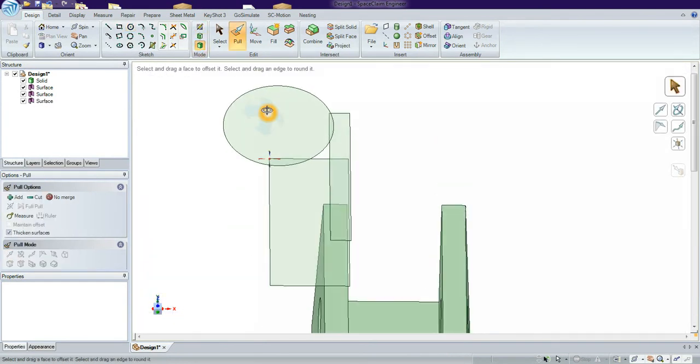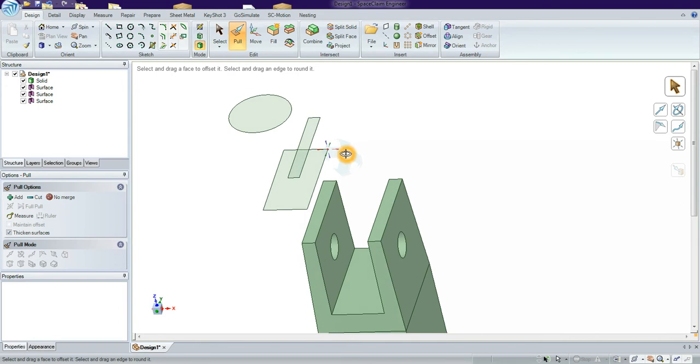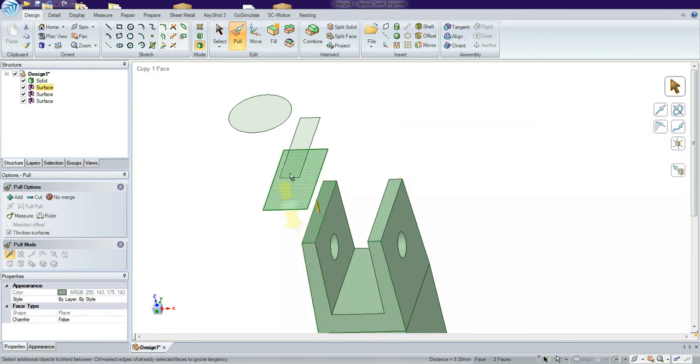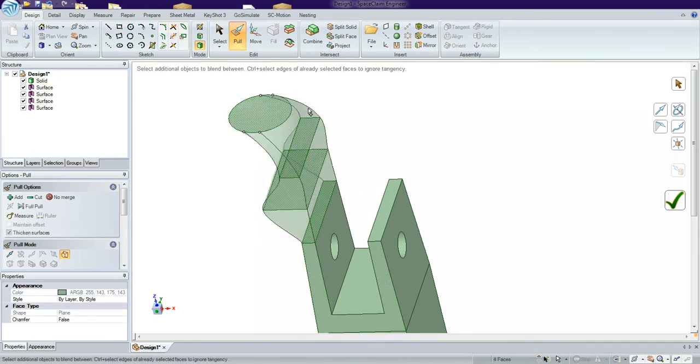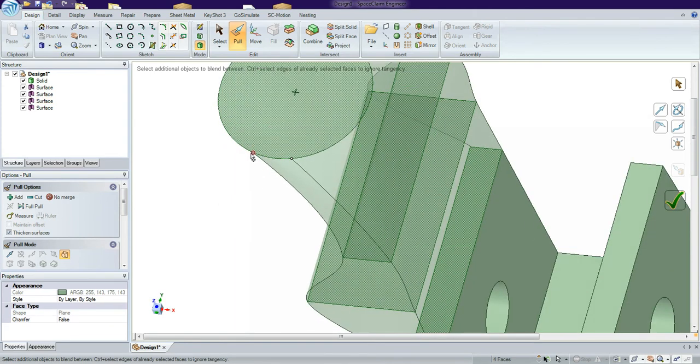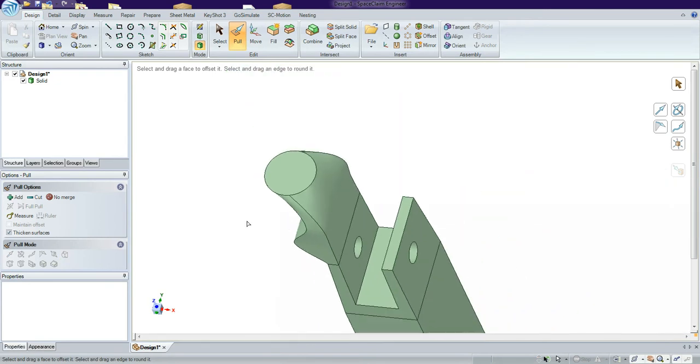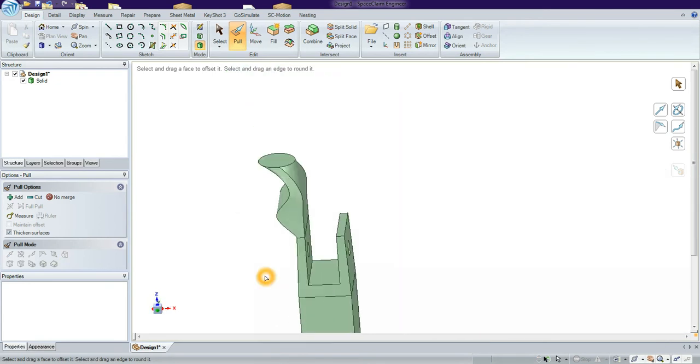Drop back to sketch mode, and you see I've got these surfaces now generated. Perhaps you want to make a little change to this one, and I'll pull this one out a little bit, and then we'll say pull from here to here to here up to here, and you can see I've got control points here, so I can basically play around my geometry and my loft. And you can see we can create quite a nice lofted shape.